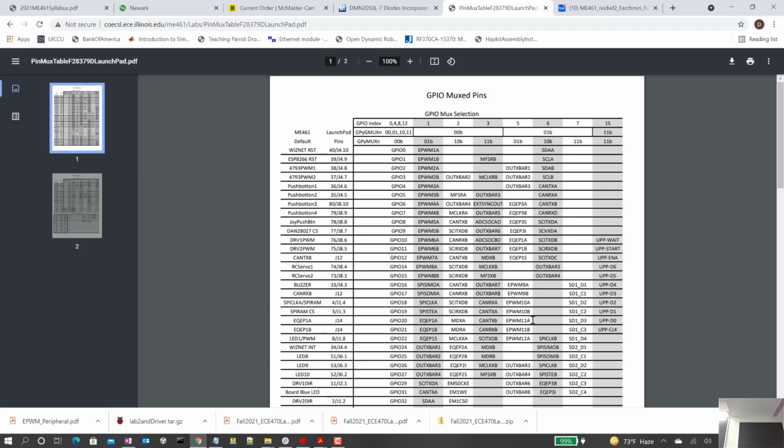And you will then, in your C code, have to set up that data pin as that function, which, if you go up the bar, is option 1. So we have these options, option 1, 2, 3, and 4 is funny, I don't know why, but they reserved it. If you set the option to 0, 4, 8, or 12, it's set up as the GPIO pin. And by default, when you power on the processor before any program's loaded, the default MUX is 0, set up as the GPIO pin.